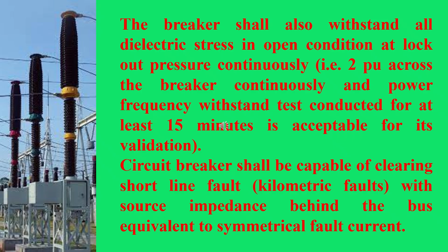The breaker shall also withstand all dielectric stress in open condition at lockout pressure continuously. Circuit breakers shall be capable of clearing short line fault with source impedance behind the bus equivalent to symmetrical fault current.